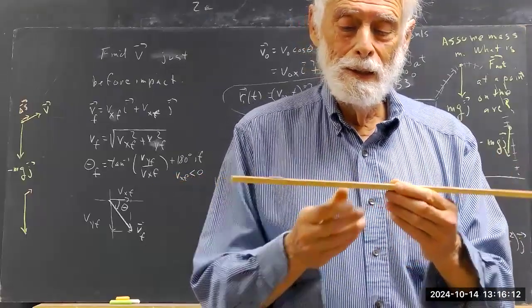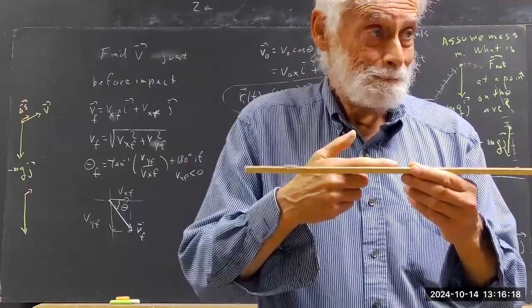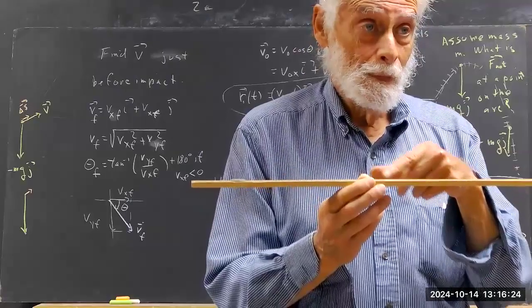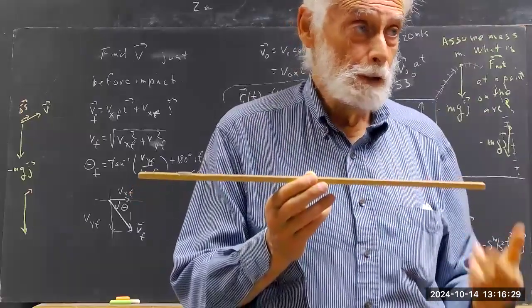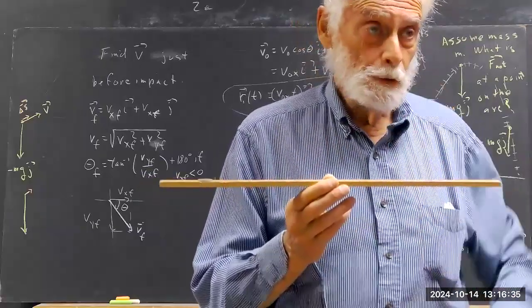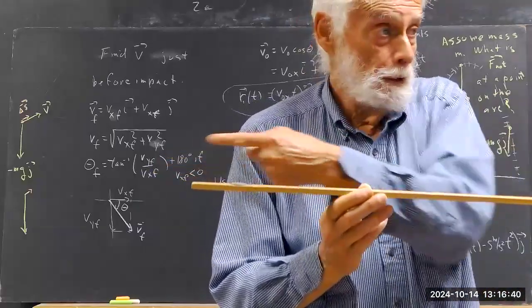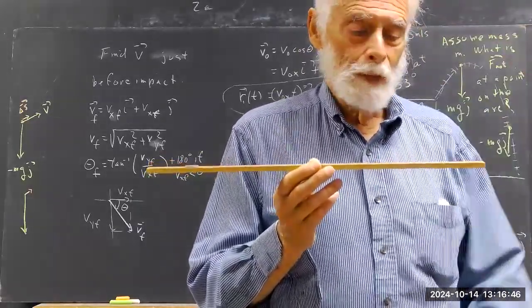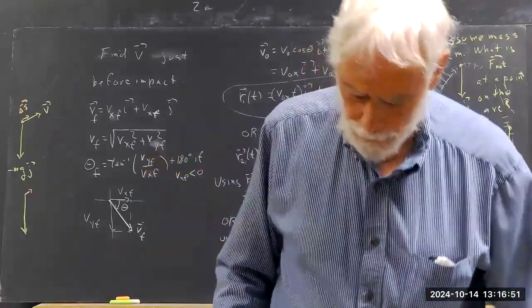And the thing that supplies this centripetal force is the frictional force. If we rotate it too fast, it's going to require more centripetal force than friction can supply, in which case, if you don't have the thing nailed down or otherwise restrained, it's going to start accelerating. Now, if you're riding on this thing, in what direction are you going to perceive this thing to accelerate? Radially, straight up. Okay? Now, there are other limitations on the acceleration. If I'm accelerating this thing too fast, it can slip off out of this.